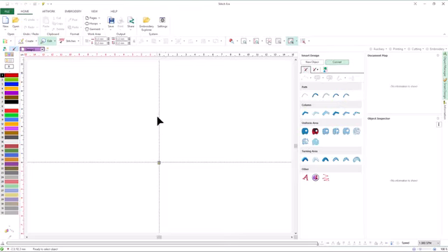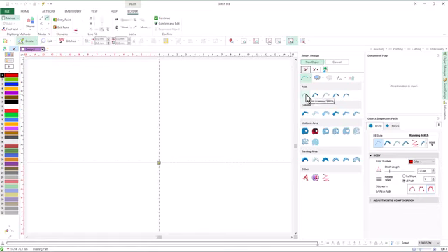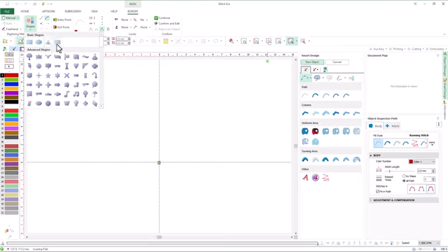Let's start creating some embroidery objects using geometric shapes as a digitizing method. We are going to create a line type object using a predefined shape, so we will use the Path tool with running stitches in this case. We use Smart Design. Select Path with running stitches and adjust the basic properties if necessary. Then, we open the Geometric Shapes gallery, pick a shape, click and drag.